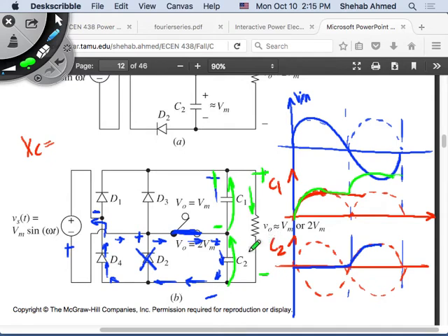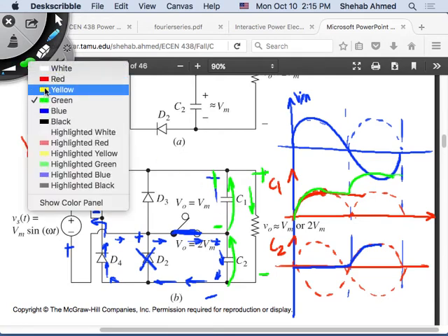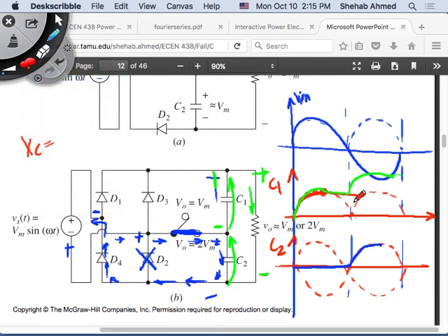Right, so the blue current, there's also another loop around here, and it cannot go, and it will go discharge, I guess. Yeah, it can go discharge this capacitor as well, and that's what's happening here, right? So we said the capacitor C1 is discharged. How does capacitor C1 discharge after the positive half cycle?